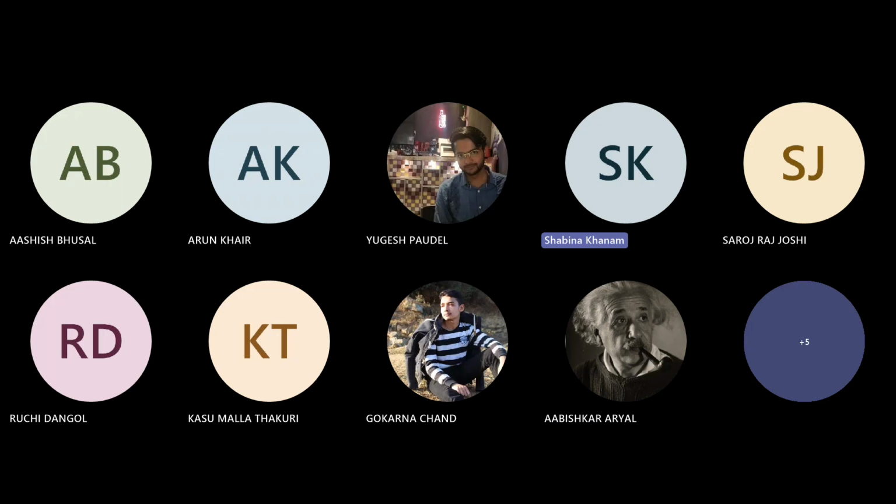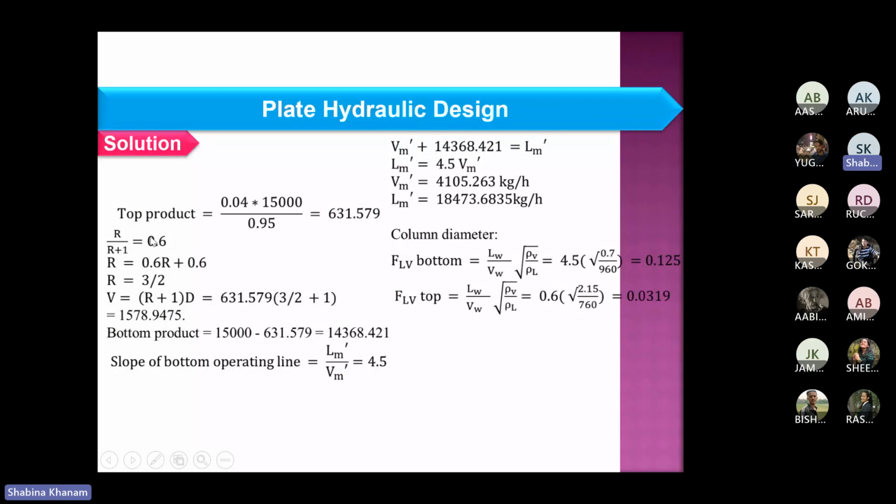It contains 95% of the acetone. Okay, so you can find the top product, that is V, and that should be 15,000 maximum I'm talking about. Otherwise, we need to consider 0.75 also, as turndown ratio. So 15,000 into 0.04 divided by 0.95, so it is coming as capital V.